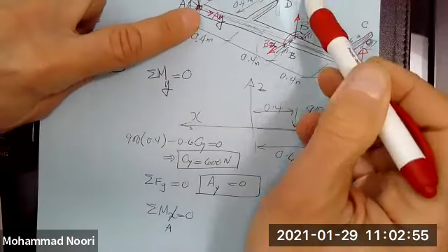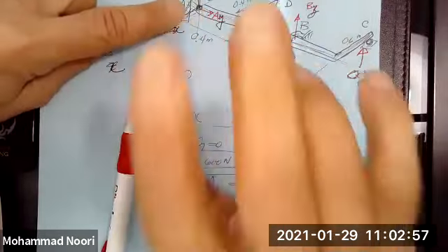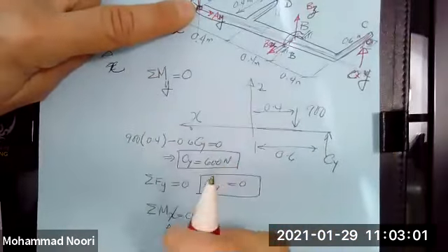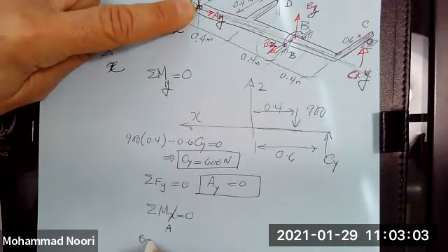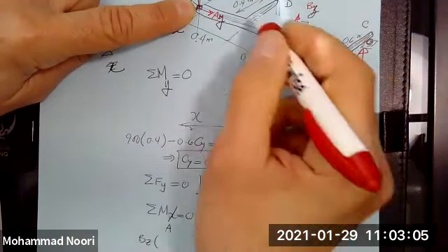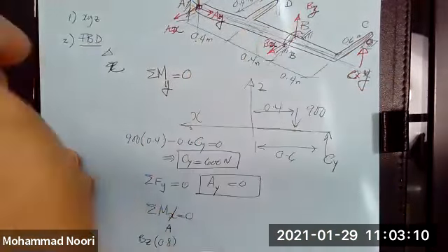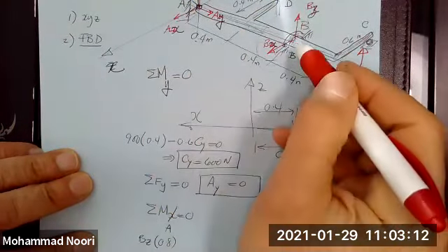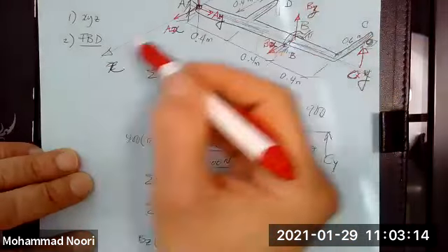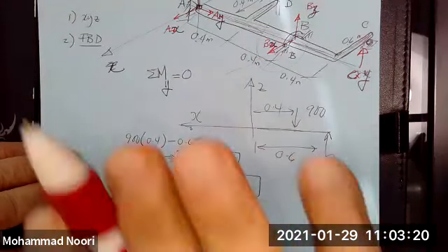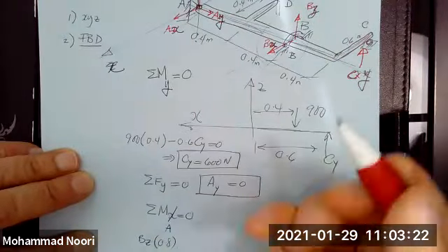So this force, which is BZ, about point O or about X, is rotating that way. So it's going to generate a moment of 0.8 times this, which would be about x. This does not generate a moment about x because it's parallel to it. How could it? This one generates a moment also in that direction.